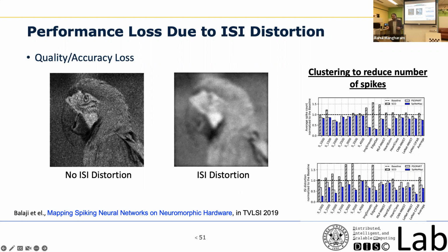Okay. Again, that depends on what frequency or how fast you are running your neurons and synapses. 1 millisecond, right? If you're running it at 1 millisecond, I would say that 30 to 40 milliseconds is what you have to hold it for. If you're running it at a slower rate, you have to hold it longer. So it's an accuracy versus real time, or energy versus real time, exploration that you can do.